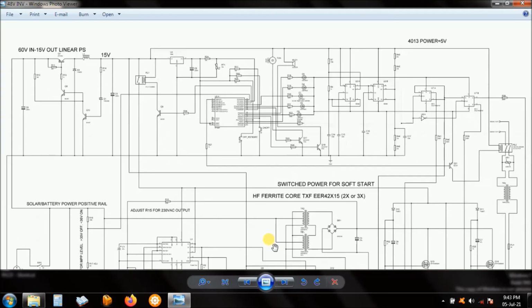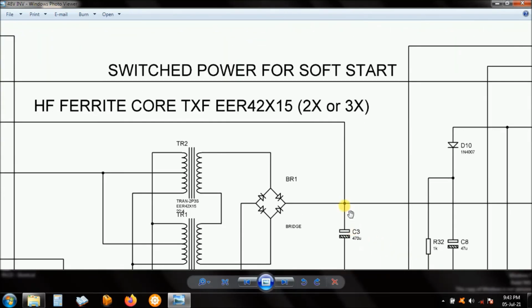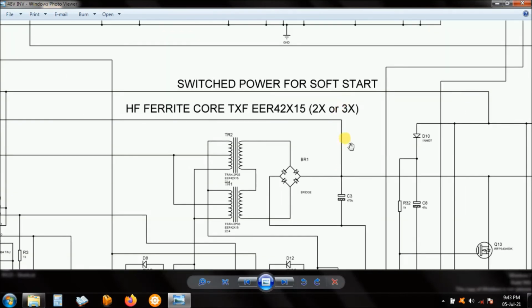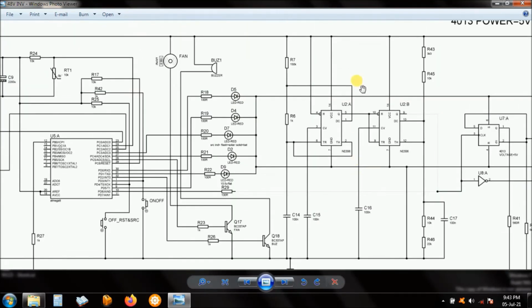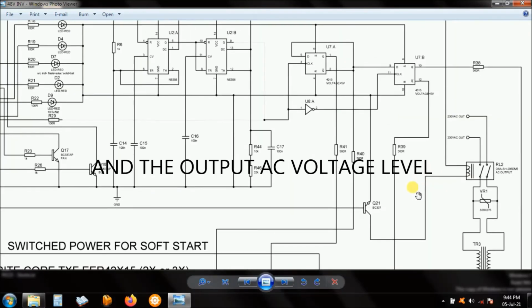They are connected to the high voltage output here, capacitor C3 here, rather than connecting to the supply voltage in megohms. Sometimes 1 megohm, 2 megohms, depending on how long a pulse you want there. So it controls the shape of the signal that is going to drive these MOSFETs.